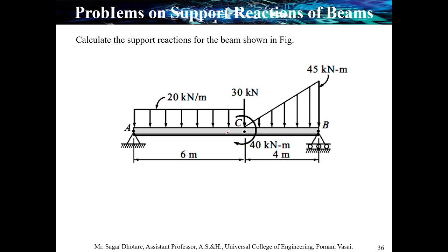Okay, in between we will discuss the basics. Again, we are recalling the types of support. If there is a hinge or pin type of support, there are two reactions: a horizontal component and a vertical component. If you have a rolling support and the movement is in a horizontal direction, the reaction will occur vertically. Okay, so it might help you in making a free body diagram.